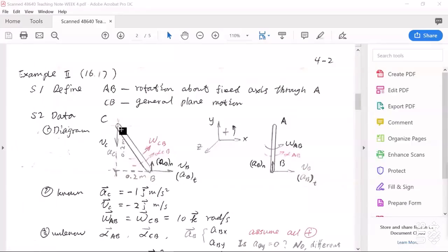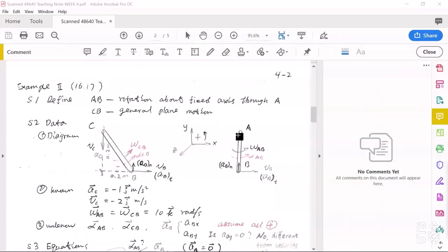Okay, now look at the kinematics diagram. Again, here, for this acceleration analysis, because vector calculation will be involved, I need a coordinate system. And here, I use a very conventional coordinate system, and I define positive rotation direction as counterclockwise. Firstly, for link AB.